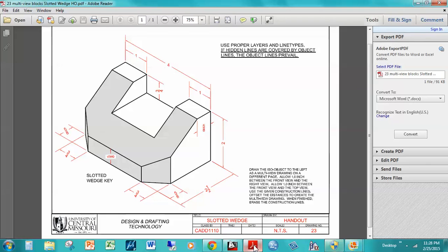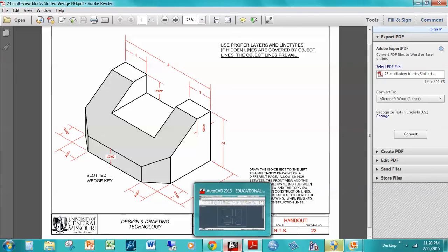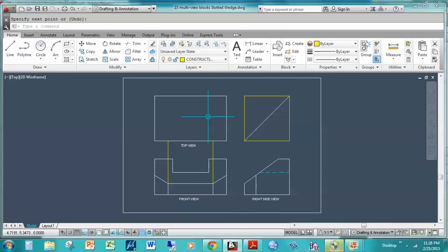Look at the handout. Do the easy parts first, especially when we have normal surfaces. So we start with normal surfaces. Here we have 1 and 5/8. So 1 5/8 and then 1 5/8. Let's do this part. Okay. Then in AutoCAD, we can offset 1 from here to here and from here to here.